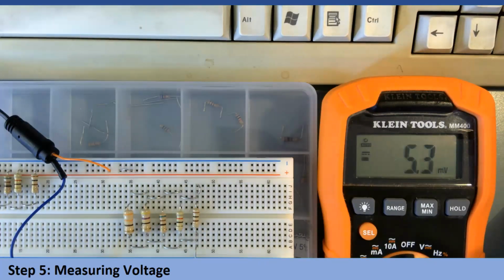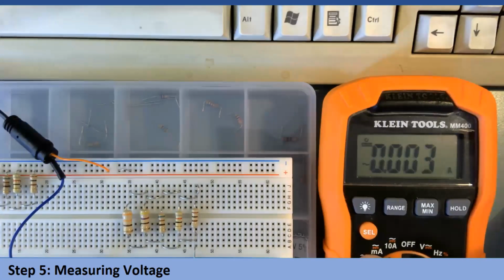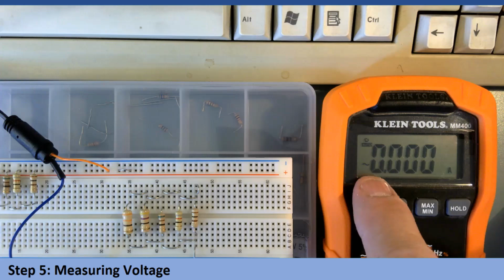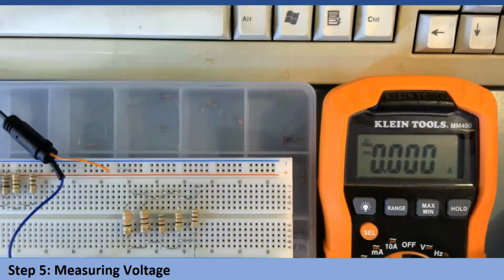That's because we are taking an amp reading. And again, amps have to be read with the meter as part of our circuit. So I'm going to change my setting. It's now on milliamps. I'm going to make sure that it's not an AC. And now I'm going to insert this into the circuit.